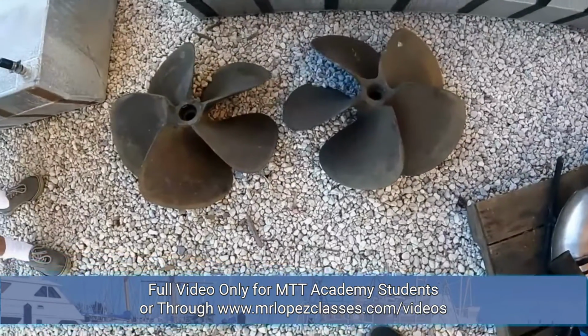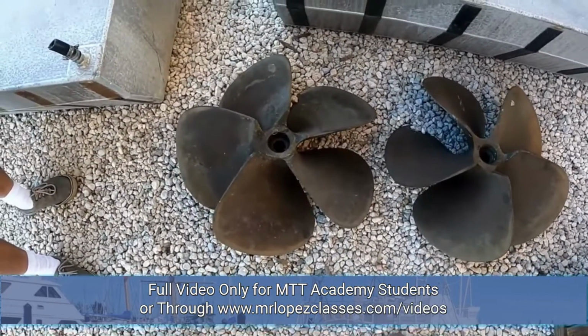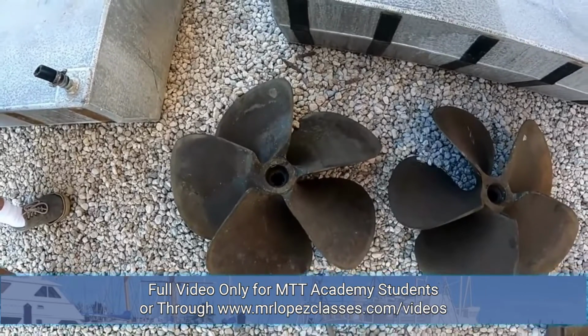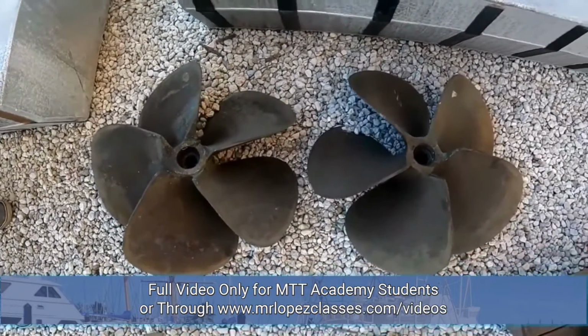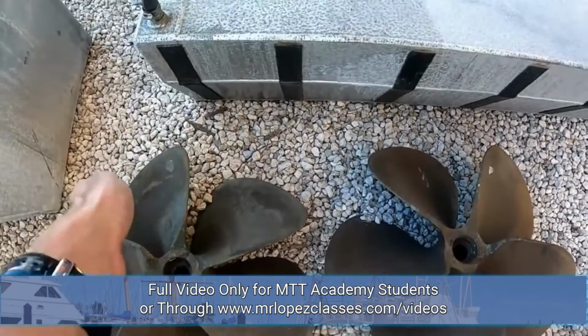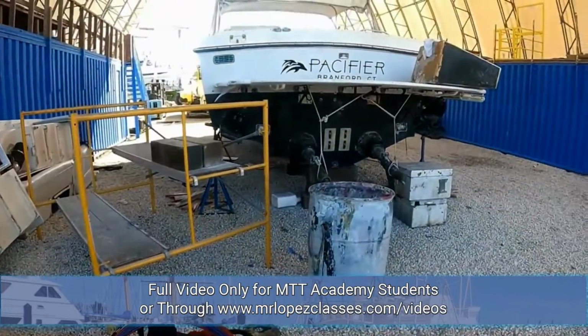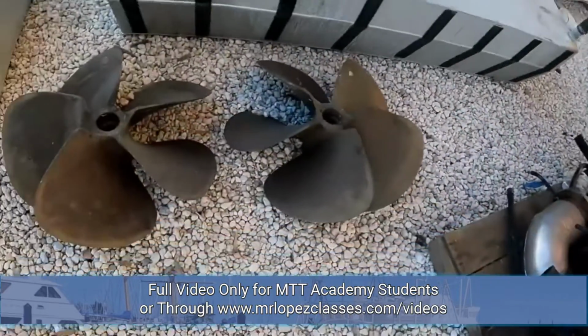These are the propellers of the surface drive. If you see, those propellers are five blades, overlap, high rake. On one propeller the blades are right side, on the other propeller the blades are left side, and those are the propellers of the surface drive system.